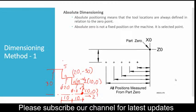Let us skip point number 4 and give me point number 5. The diameter at point number 5 would be what? It would be 30 in diameter. Nice work, guys. And 10 plus 10, it would be 20 in depth. So it is 30, minus 20. Do you get the dimensioning pattern using absolute?